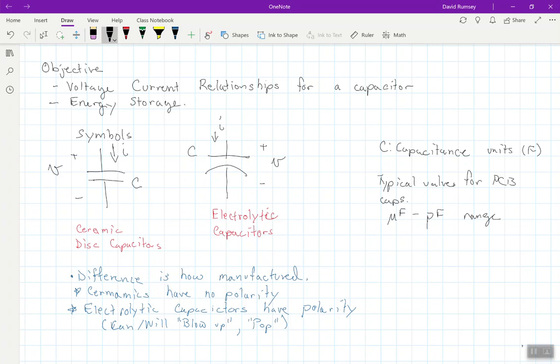That's not to say that you can't get millifarad capacitors. There are millifarad capacitors, and those tend to be used for high power applications. They are very dangerous, those larger caps in the millifarad range, because the amount of energy they can store can actually kill you if you aren't careful with discharging the cap. So depending on the size of the capacitor, they can be very dangerous.